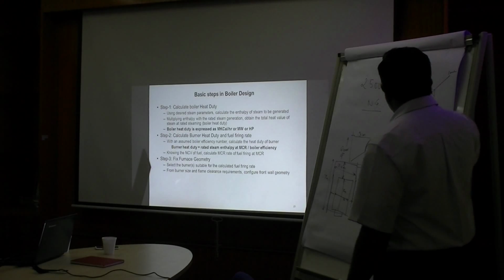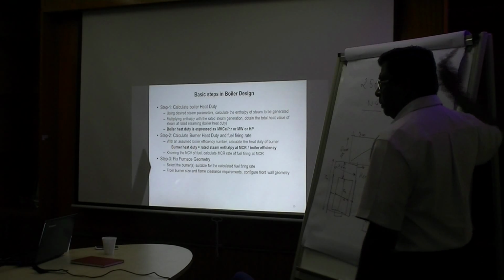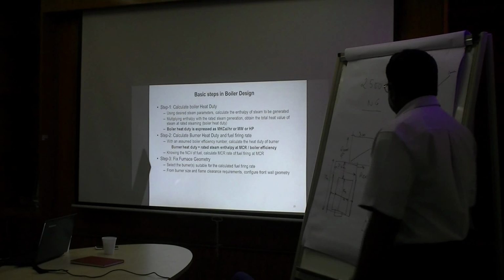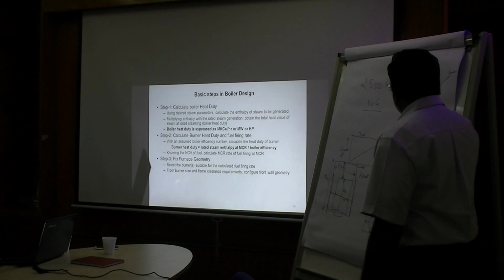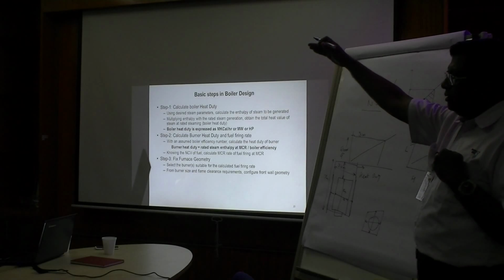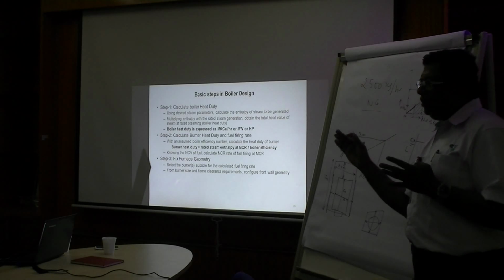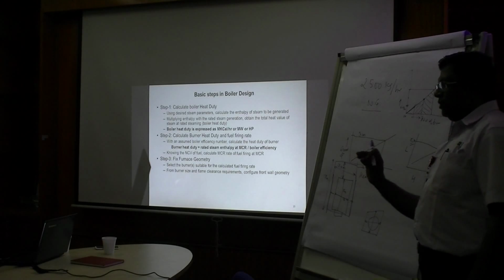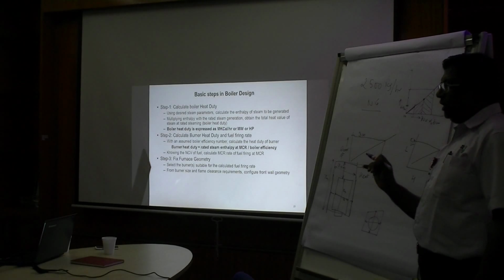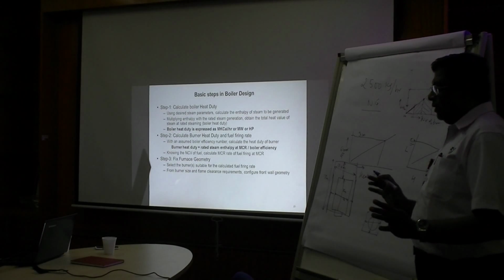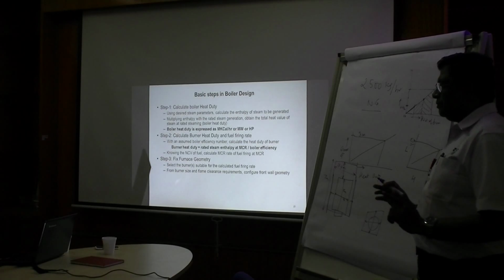So it's like a step: every time you come to the end of a step, you change to the next number of burners. Let's say you are just at the border point, already at the full capacity of 2 burners, and even 5 tons more means you have to go to a 3rd burner. Then you take a conscious decision whether you want to really worry about it, or you just manage with 2 burners, pushing them to their limit.